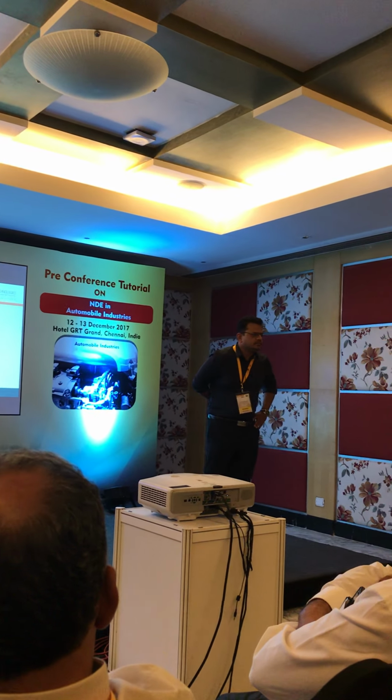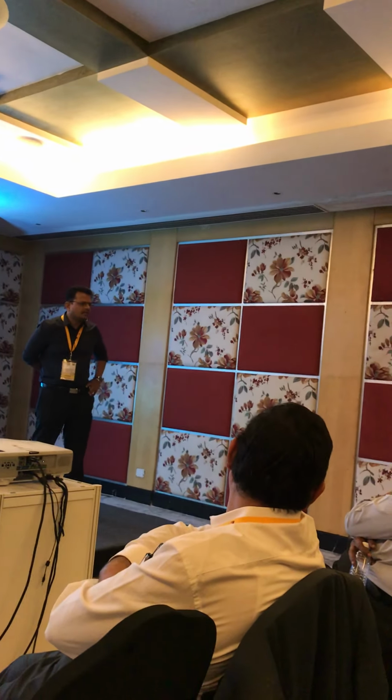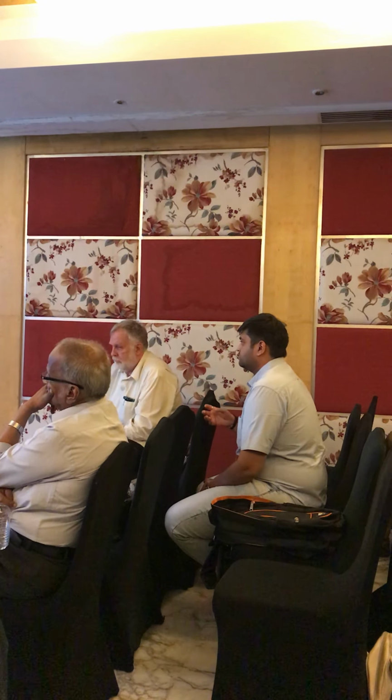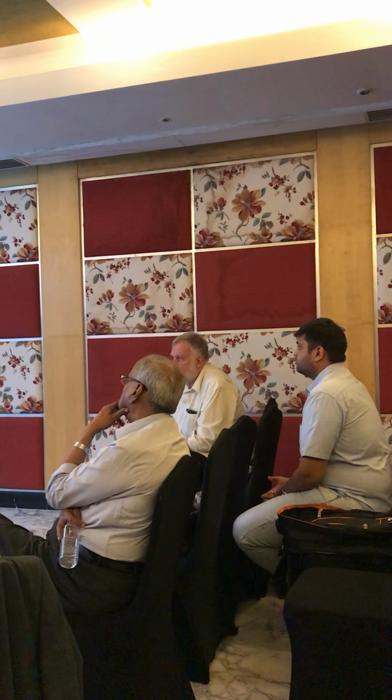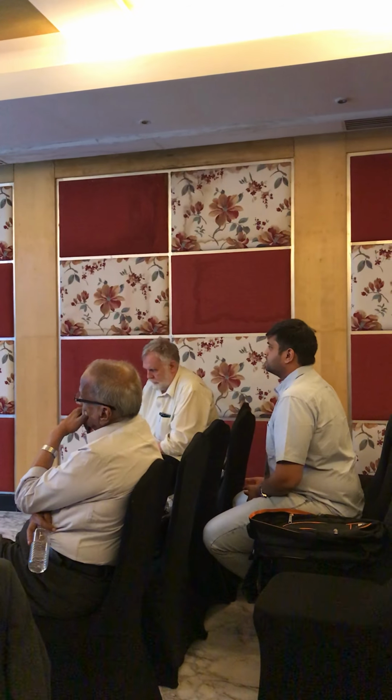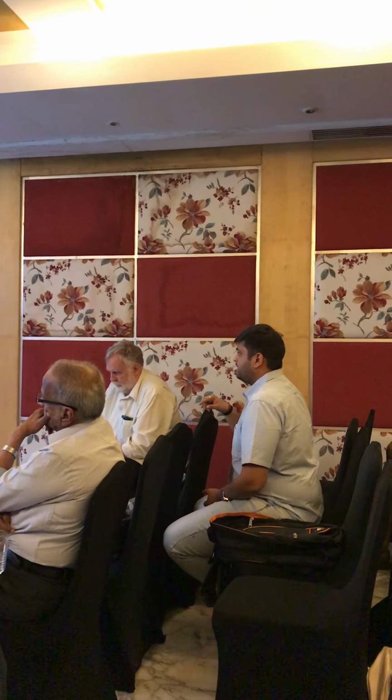Even if we are getting noise, because I have faced something like this: there was a defect, but it was showing like noise, a noisy part. It was a brass metal. So in that case, how can we differentiate between a genuine defect and noise? With thicker parts and high-density material, there is inherent unsharpness, total unsharpness.